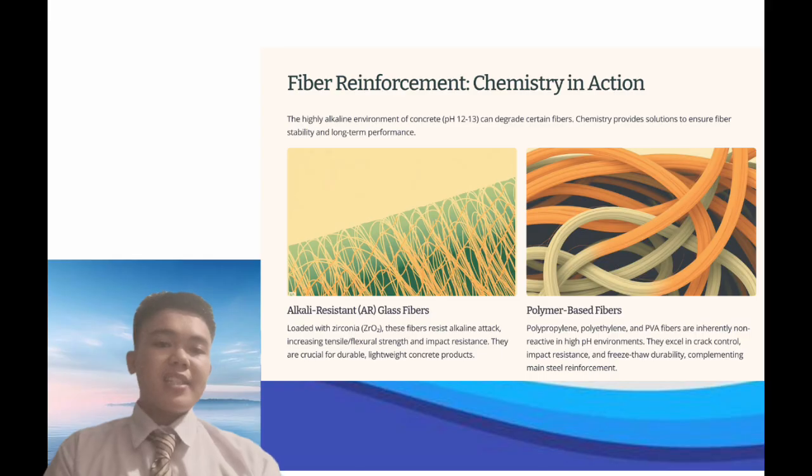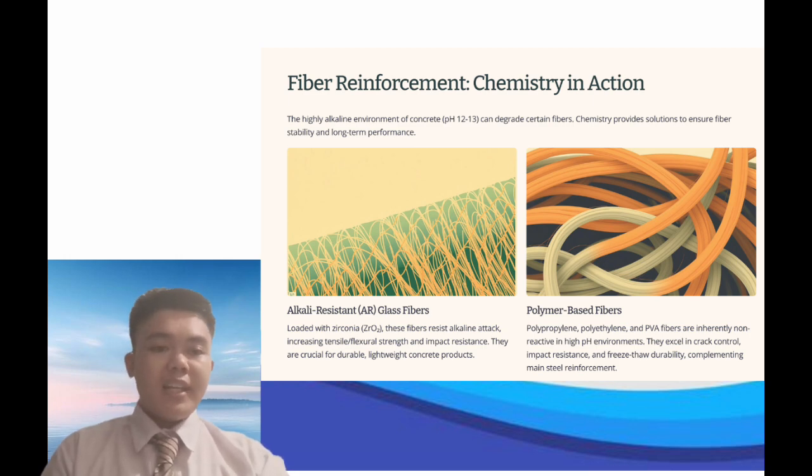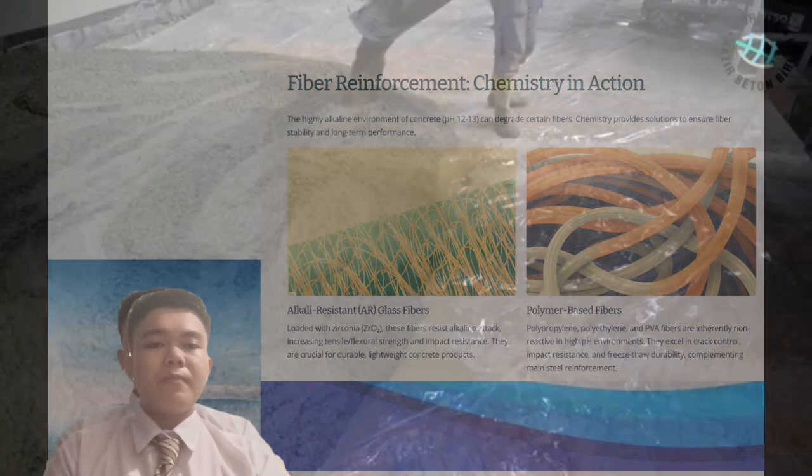They increase tensile or flexural strength, impact resistance, and cracking resistance, allowing for thinner, lighter concrete products such as ornamental panels and pipes, and can replace steel in some applications because of their non-corrosive, high-strength qualities, which allow glass fibers to last for decades within concrete.